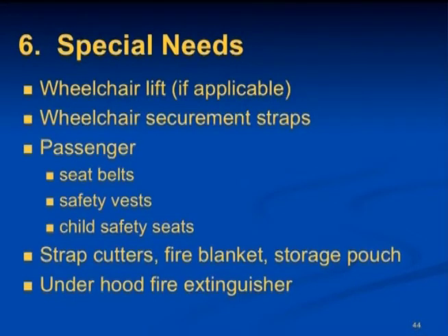Make sure all the special equipment needed before you take the bus is on the bus. The wheelchair lift, if applicable, should operate smoothly. Make sure no cables are caught when folding in the lift. Wheelchair securement straps should be neatly stored to prevent damage to tie downs as well as to the passengers and their wheelchair. Passenger seat belts should not be frayed and latches not damaged.